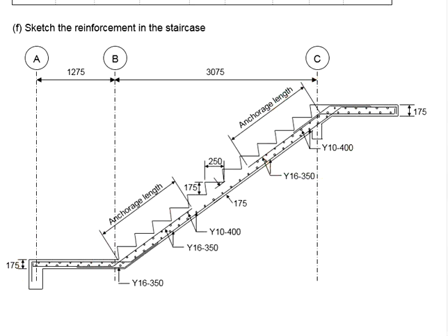You will also need reinforcement at the top of the staircase, especially the regions near the support. You know that the concrete is cast monolithically to the beam. That means you are going to expect a certain degree of negative moment at the support. That's why you have to provide the top reinforcement at the support. When you provide the top reinforcement at the support, the arrangement of the main and secondary rebar will be the opposite to the bottom reinforcement.